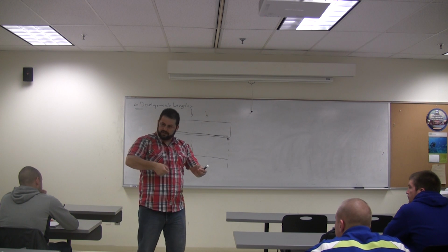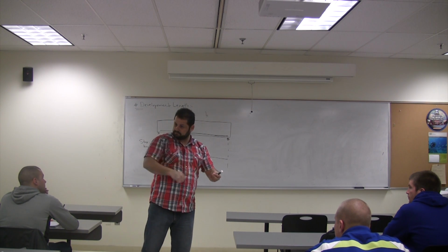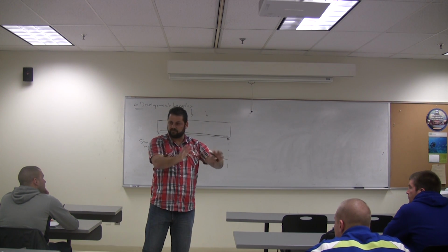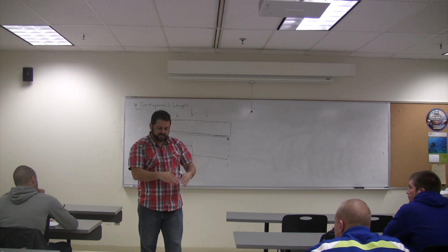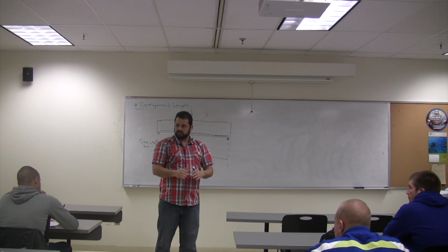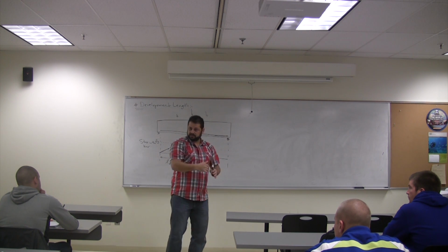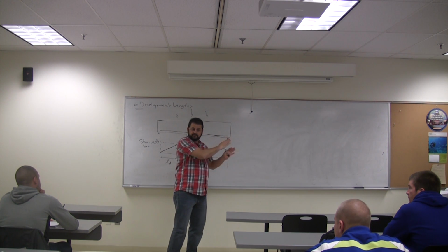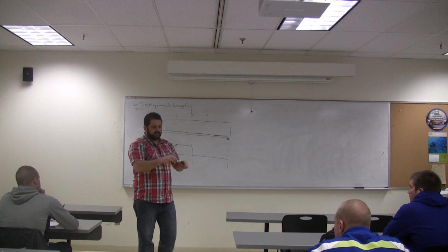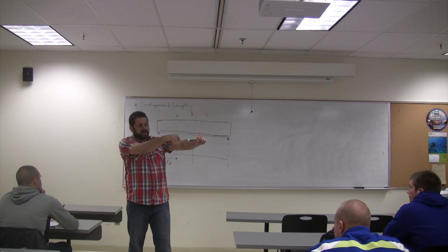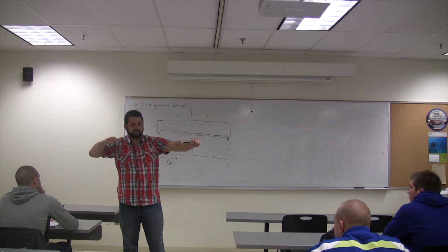They bring the first one, they plant it in the concrete 10 inch. They cast the concrete, it develops strength. Now it's planted in the hardened concrete. The second one they put 20 inch. The third one they put 30 inch, 40 inch, 50 inch, from the same series. Then they go to the one with the epoxy. Same. Then they bring a machine, a pull-out machine, a direct tension machine.